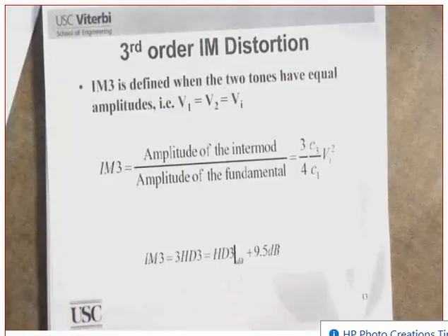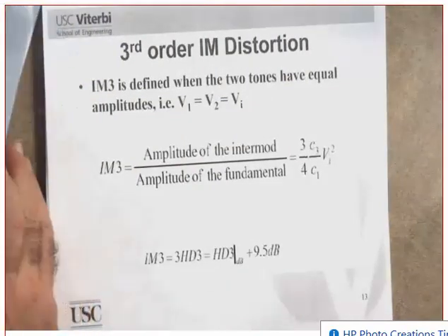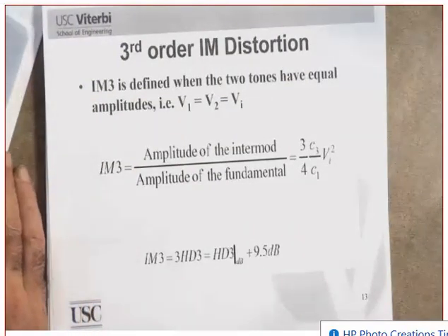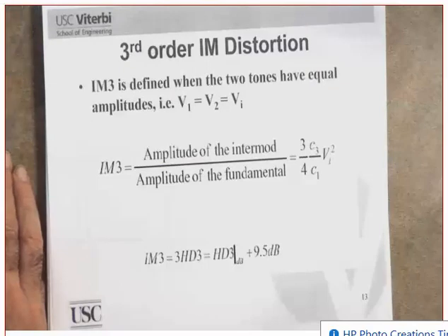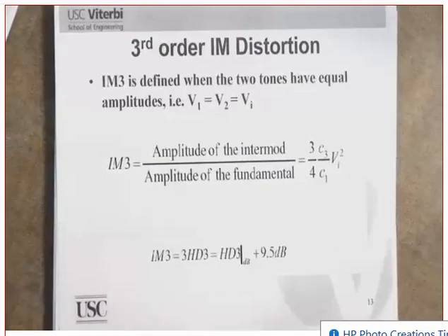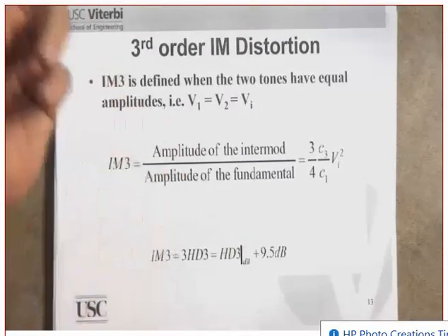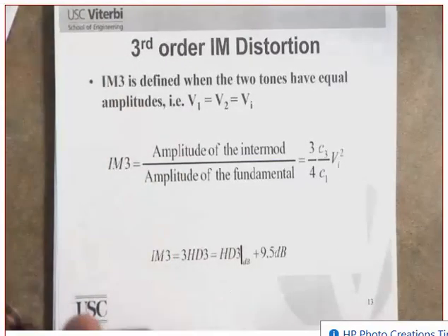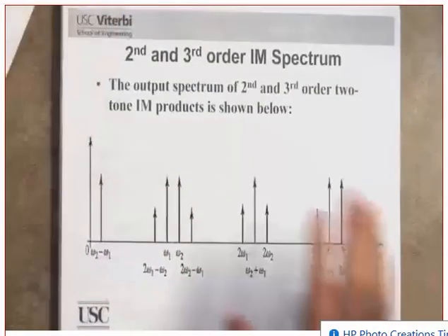Okay, which means what? It means that the intermodulation, third order, intermodulation component is roughly what? 10 dB more than the what? More than the what? The third harmonic component, distortion. Clear? High or low? It's relatively high, 10 dB more. Clear? Okay, good. Now, combine them together.